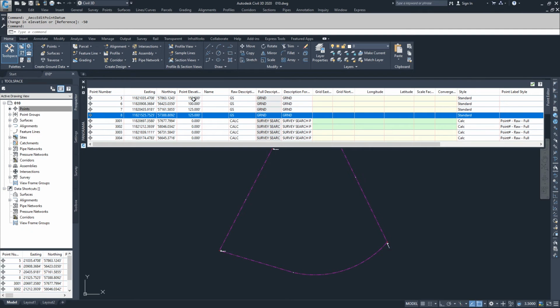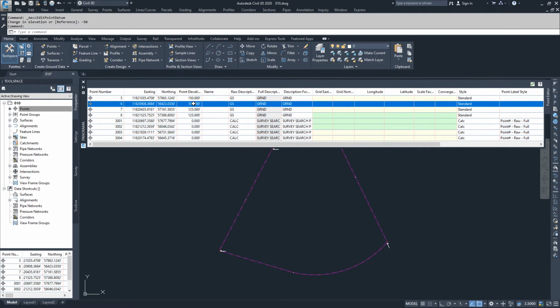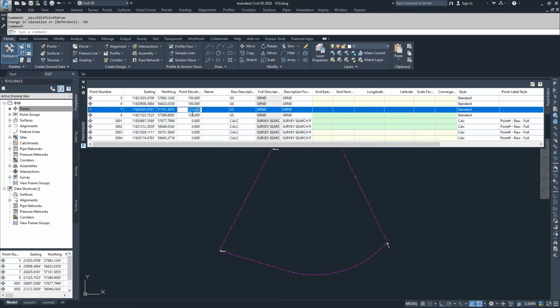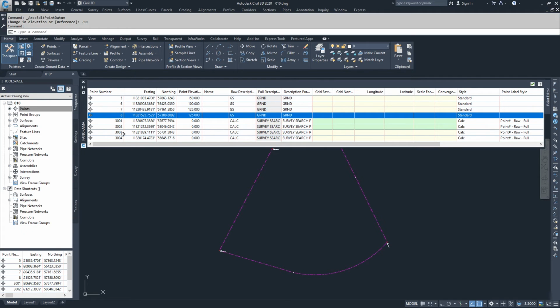And you could adjust each of these points individually by selecting them and adding 50 feet to them. The other thing that you can do while you're inside of this Panorama window for editing points is adjust your easting and northing of the points that you've selected. Say you had a point readout of what a specific location was and what elevation it was, then you could change those eastings and northings and choose an elevation based on that point readout, and then it would modify it in the drawing down here.